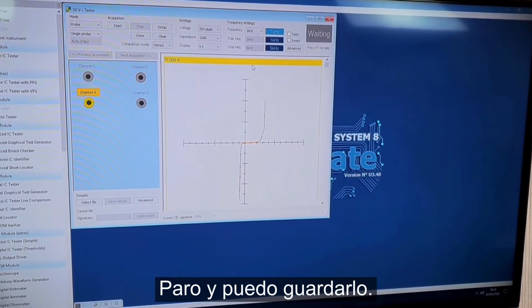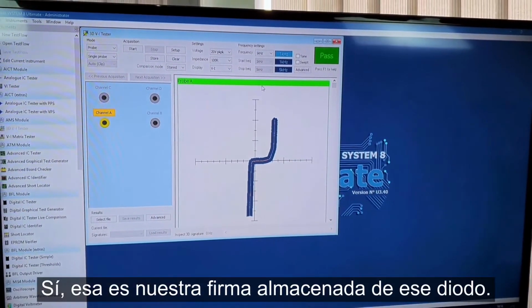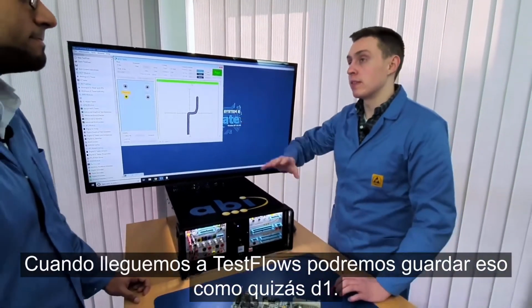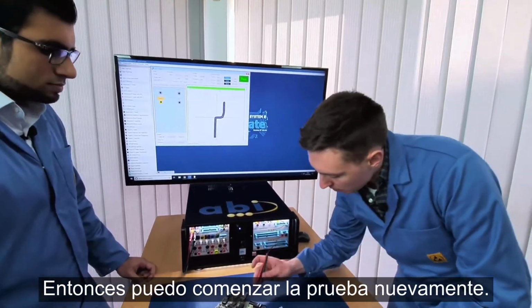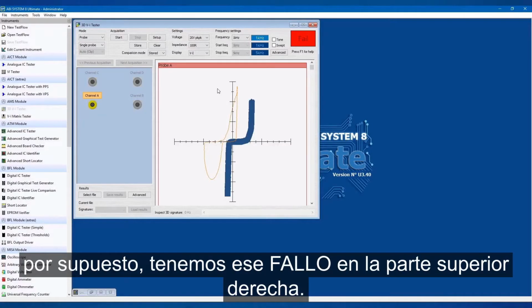And I can store that. So just to touch upon here, this blue line that we see, this is the mask. Yep, so that's our stored signature from that diode. When we get onto test flows, we'll be able to save that as perhaps D1. Right. So and then I can start test again. I can compare that against the other diode, completely different. And then of course we get that fail in the top right.